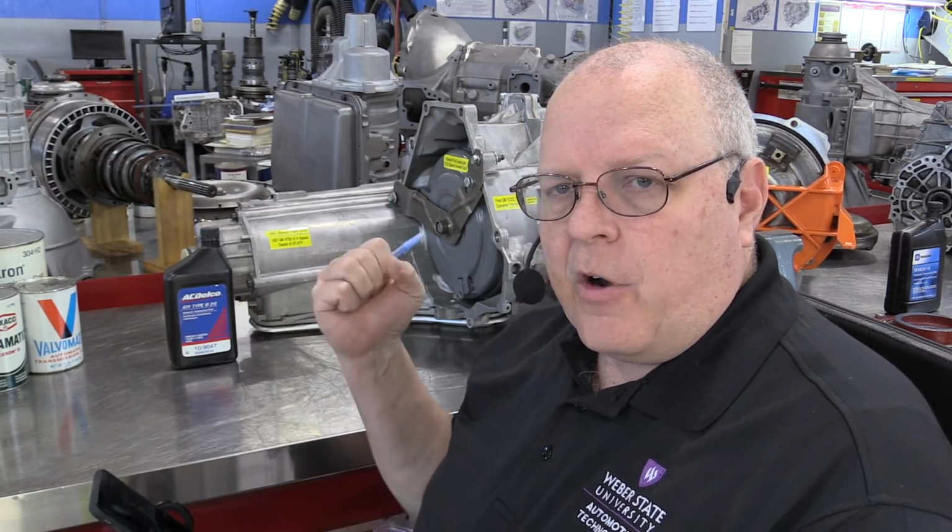Now, the change to the Dexron III automatic transmission fluid, I believe, was just a natural progression as the refining methods for base stock oil improved and the oil itself improved. But there was also a new technology on the horizon coming up for the 1997 model year transmissions. And I've got the very first transmission here behind me that has what's called an electronically controlled clutch capacity torque converter clutch. So the ECCC.